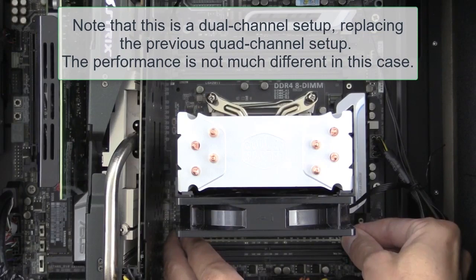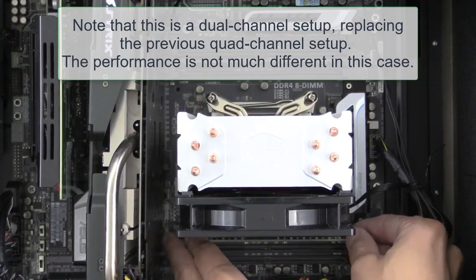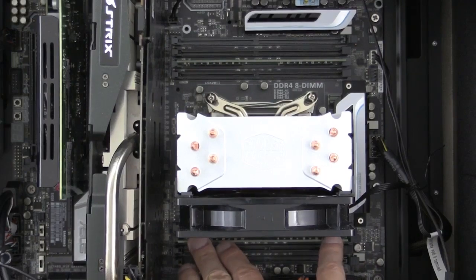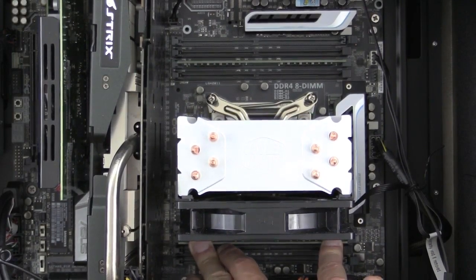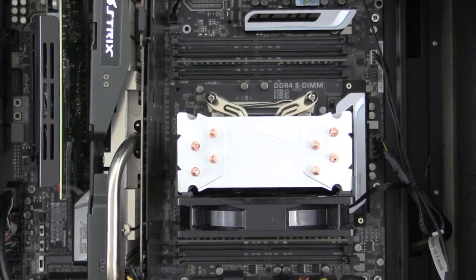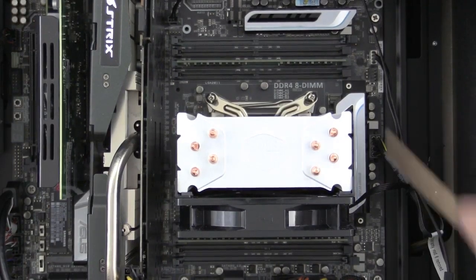Trying carefully not to touch any of the circuit boards. Slide it straight in, and then we'll press down until it snaps into place. There we go. And what I was doing was I was applying even pressure to both sides, trying at the same time, so that we don't bend the RAM and we don't bend the motherboard too much.